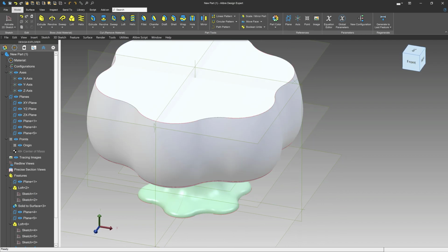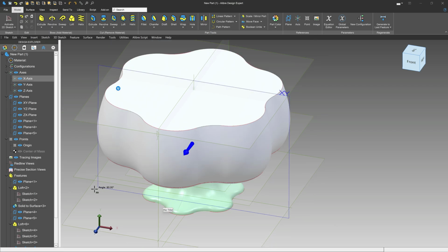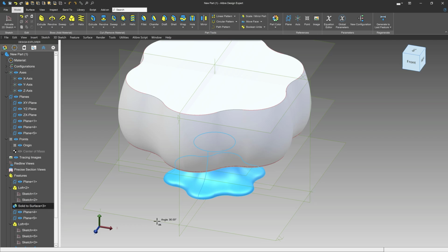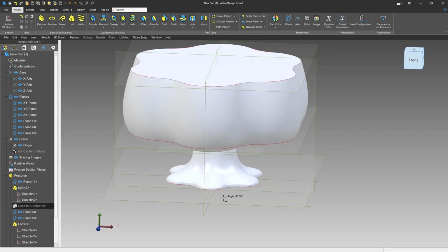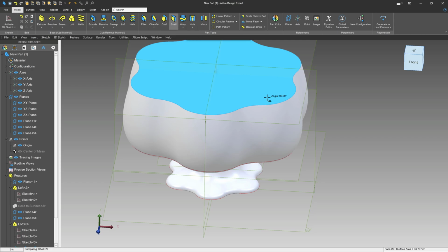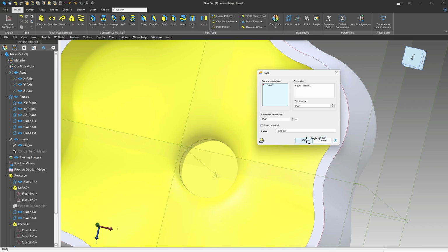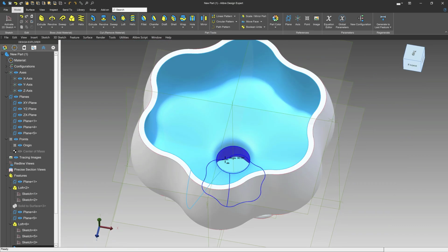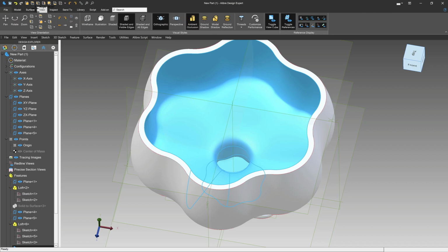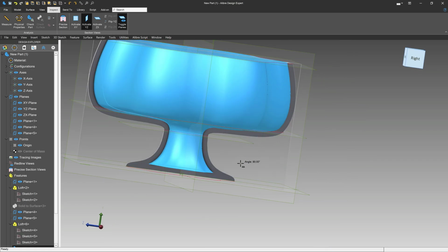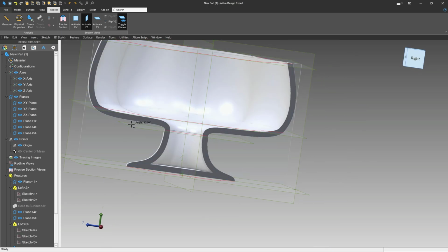So then the big question comes, why did I convert this base to a surface? And we can see why, right? If I go to the solid to surface and I suppress it so that we're all solid, no problem, and then I go to shell, right, we're shelling all the way down. And it's not very realistic. You can't get your spoon in there, right? How would you like to have some tort that you just wouldn't be able to eat? So when you go to inspect this, you can't fit a spoon in there. So it doesn't make sense to have that, right?